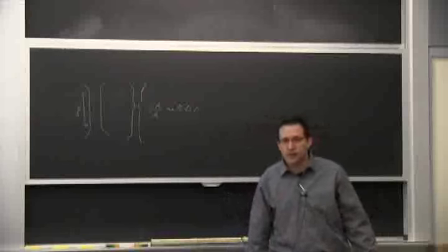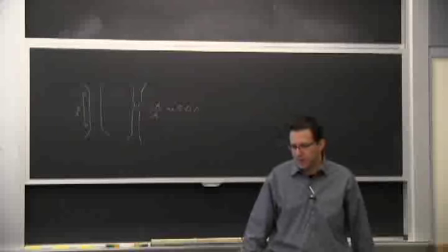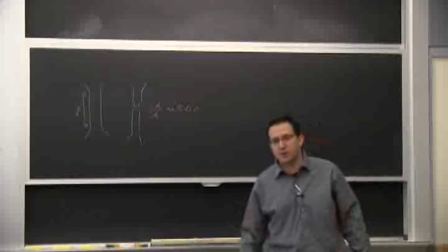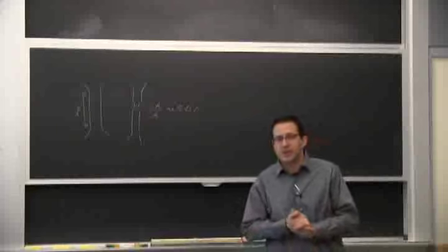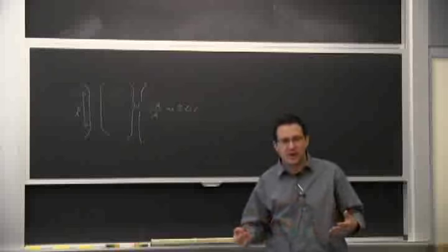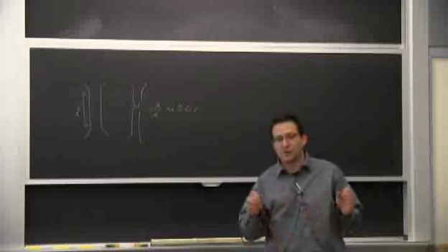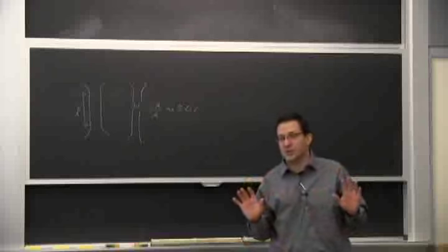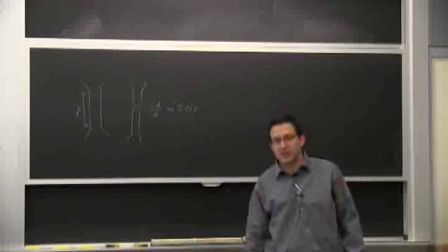Today is mostly intended for metals, because we talked about metals as being more resistant, if you will, to having small cracks in them. That's why we can design them with pre-existing cracks. It's a safer approach than having to assume that the surface is really good, because in practice it's not always going to be the case.